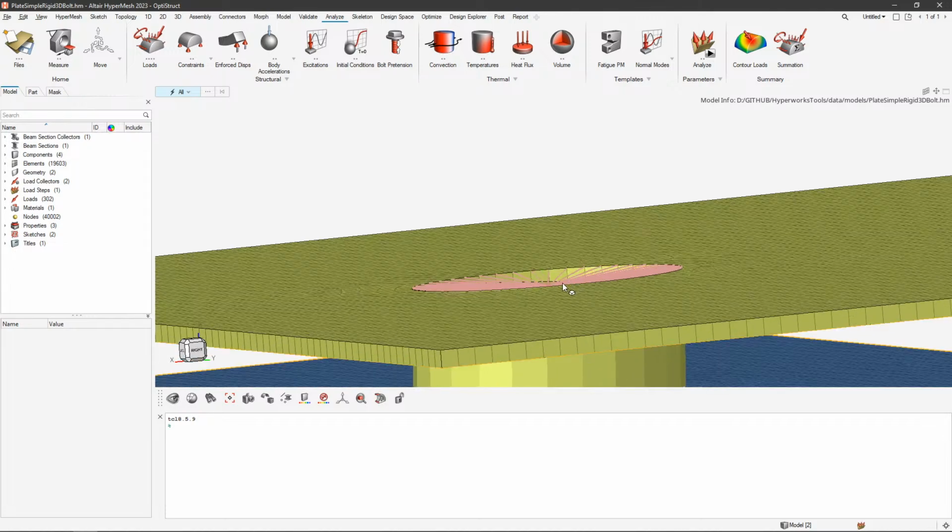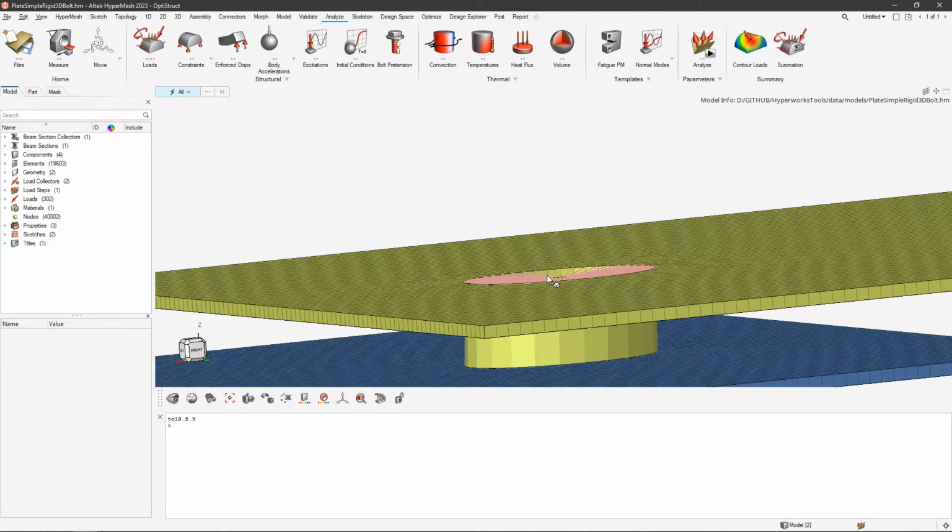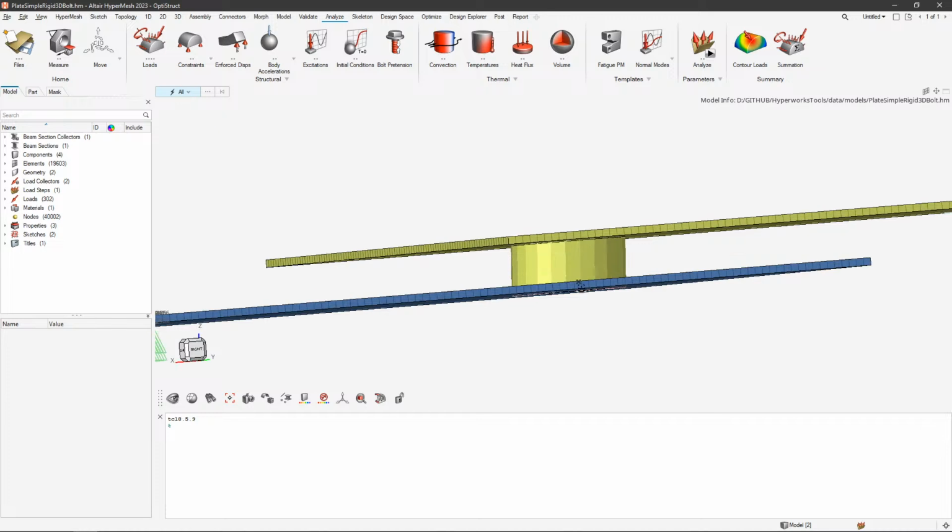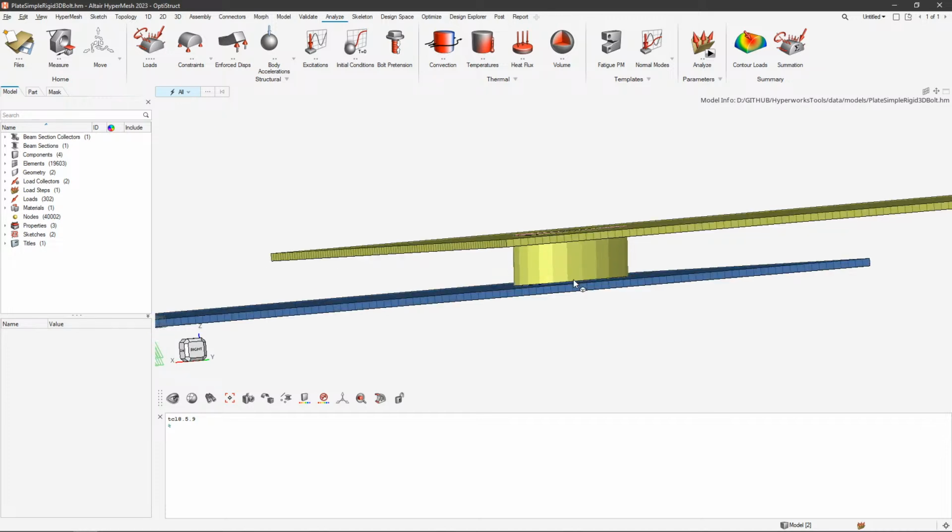Now, if you know the force being transferred at this location and that location, wouldn't it be possible to just have something like F divided by A for a stress formulation and have some rough estimate if the bolt will hold or if it would break?